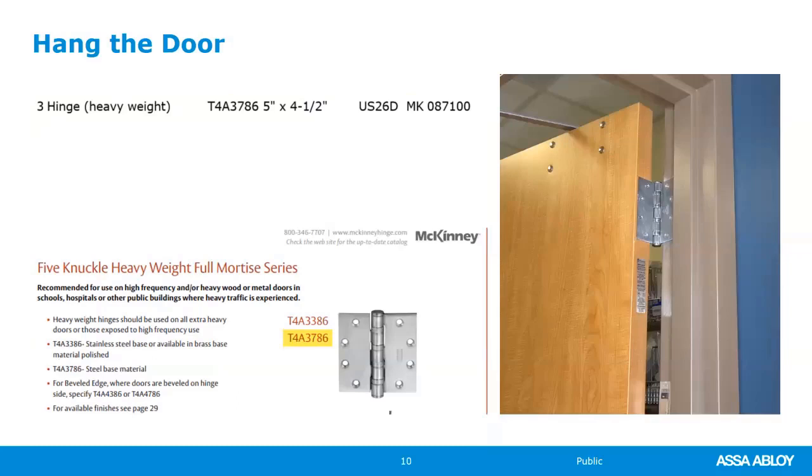A clean workroom is a storeroom, and a storeroom will get quite a bit of frequency of use. So it is a wide, heavy door. Heavyweight hinges were selected, 5 inches high, because anytime we have a wide door, the taller the hinge, the more it helps disperse the weight over the height of the opening. And so 4.5 inch wide, the door only needs to swing a little over 90 degrees, and a 4.5 inch wide hinge could allow this door to swing 180 degrees if there wasn't something behind the door blocking the door.